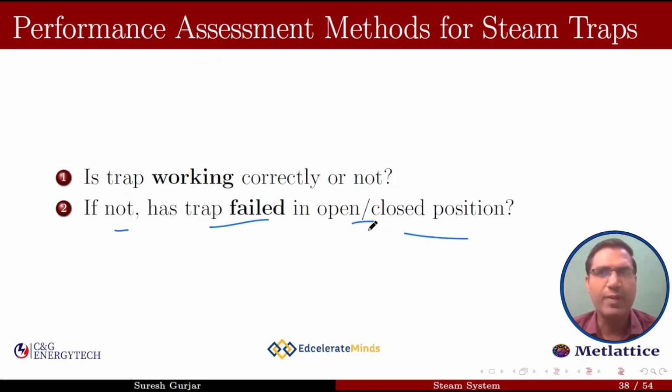When the steam traps fail open, it means they continuously allow the steam and condensate to pass through. Steam traps that fail open result in a loss of steam and its energy. When condensate is not returned, the water is also lost as well. The result is a significant economic loss directly via increased boiler plant costs and potentially indirectly via decreased steam heating